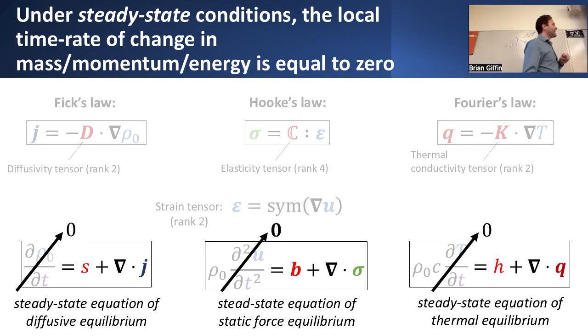And we could think of things happening in this sort of transient sense where there's a dependence on time. And in fact, if we wanted to include dynamic behavior of, how does this chunk of material speed up or slow down or vibrate under imposed loading conditions, we can include this extra term here. But it so happens it's particularly convenient, at least in our initial investigations, to just assume things are at steady state. Things aren't moving around. Things have settled down into their relative equilibrium states such that there is no relative change in density with respect to time.